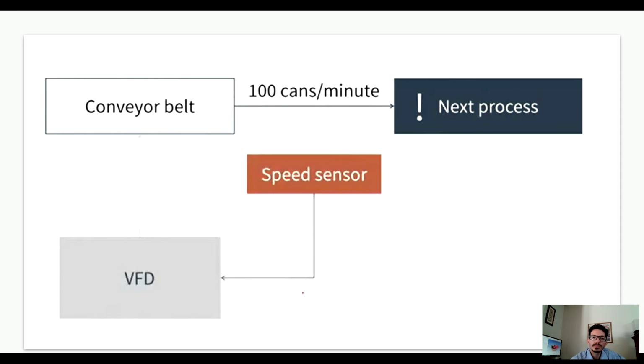So a belt can go faster or slower, and of course the sensor will be tuned to the velocity to be able to capture the can passing through the sensor, and you can vary your production time with the velocity of the belt and the amount of cans that you can read per minute, etc. All those processes that can be tailored to have different timings usually have, underneath, motors and applications with frequency drives that can change the velocity or the speed of the process.